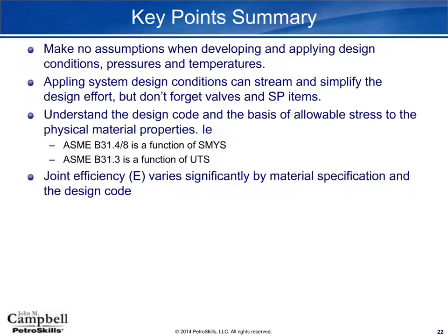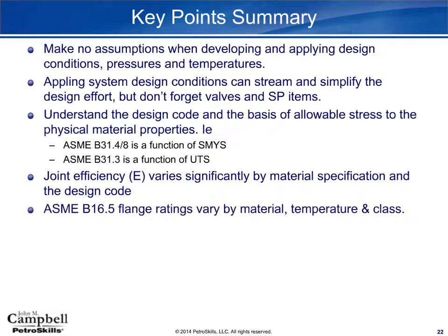Also your flange ratings, whether you've got an API flange or an ASME B16.5 flange, those flange ratings vary according to the material and the class, but temperature is also a factor in here. So when we start talking about specification of materials, just be cognizant specifically of those issues surrounding stainless steel flanges. There's a big difference to carbon steel flanges, and the actual grade on flanges and on valves is also a factor.